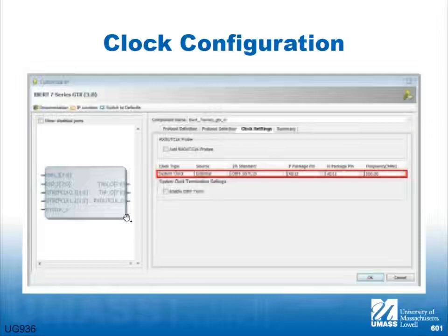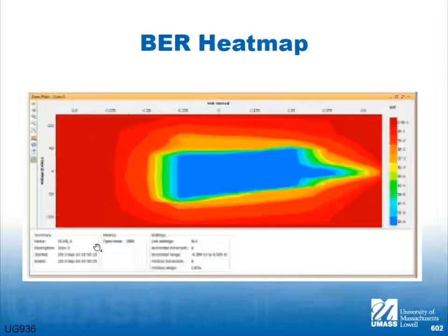If you're actually designing a high-speed interface, all this stuff would matter. And you get a nice pretty picture, which is the eye diagram, right? So as the signals transition from low to high and high to low, like let me draw, up, over, down, and over, down, over, and up, right? This is the area where the signal is in transition, right?